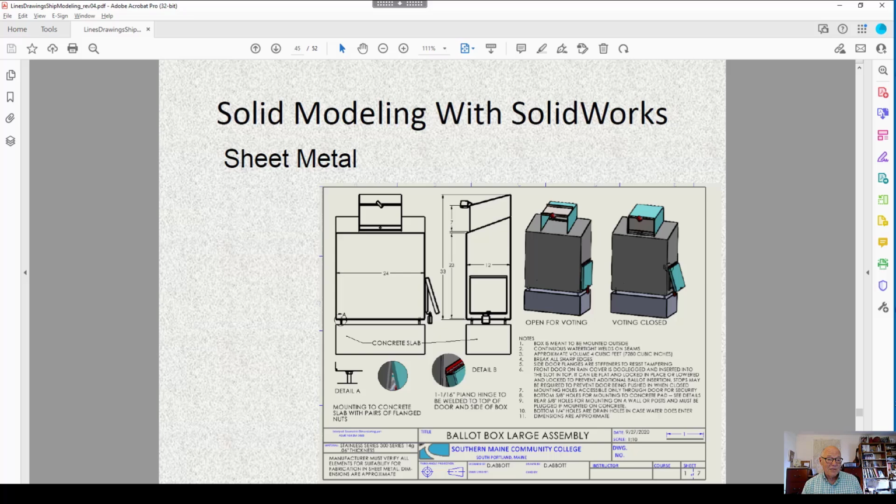It looks like just a box with a slot in it, but for one thing, it has to have a cover for rain, and that slot has to be back there so that if the rain is being driven by wind, it can't then fill up the box with water. And the wind-driven rain of a 100-year storm would come at an angle that is just shy of enough to get in there. So that's what I was doing as far as the design goes.